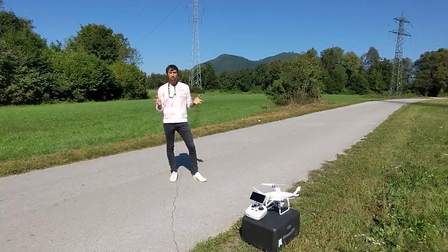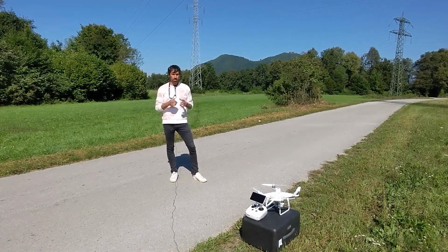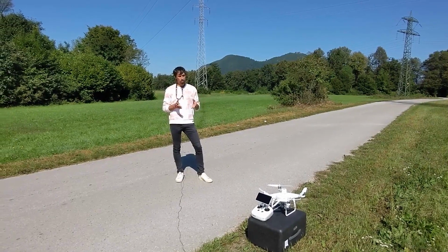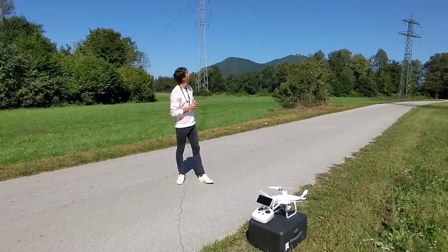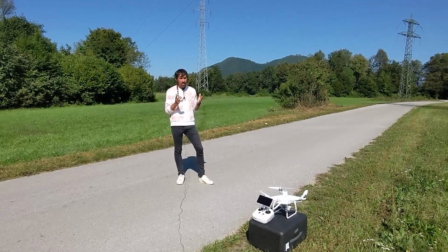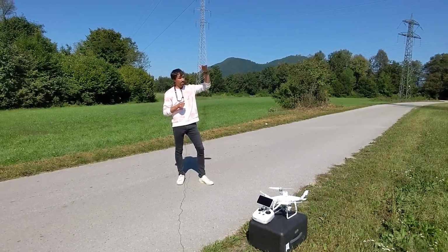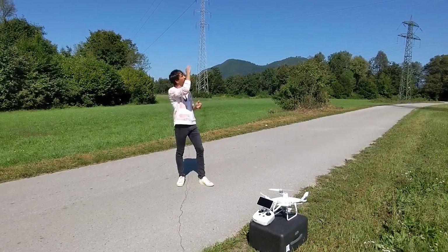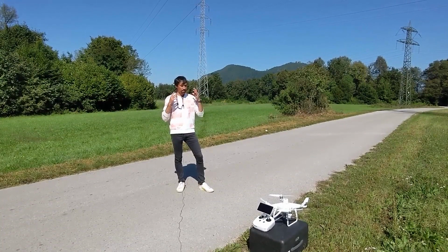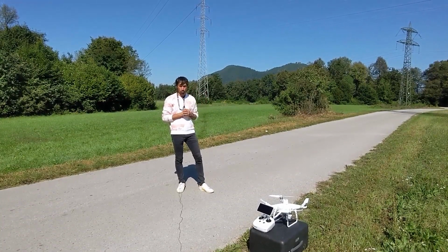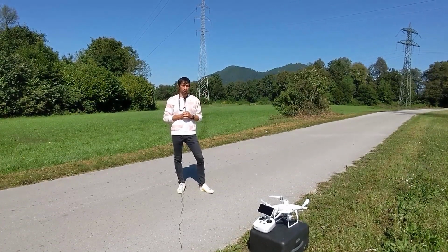We are not going to use ground control points for this project because the accuracy of the integrated RTK GPS is more than enough for this kind of project. We need more or less relative distances between cables and terrain, and the accuracy is more than enough without ground control points if you use such an RTK drone.